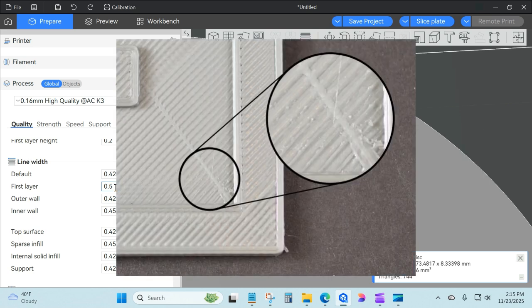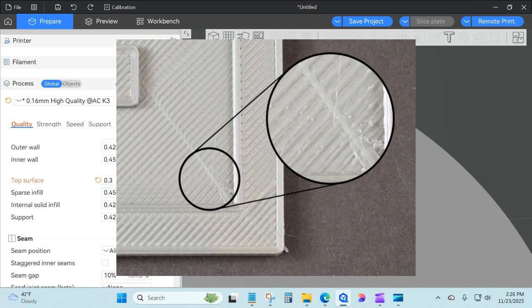If your nozzle's dragging on your model, that means you have too much plastic squished together, which then created it to bubble upward slightly. How many times have we seen an image like this one as a cry for help in every 3D printing forum out there? Help, these lines. My nozzle's dragging. I can hear it dragging. We've all seen it. And if you're new here, hi, you're going to see this a lot.